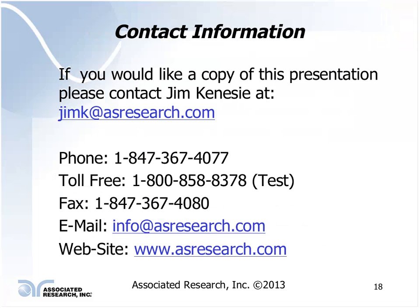It says, if my product passes the DC, would it pass an AC test? Should I use one or the other? Okay. Again, depending upon the safety standards, if you do pass a DC ground bond test, it will most likely pass an AC ground bond test also. There really doesn't seem to be much difference.